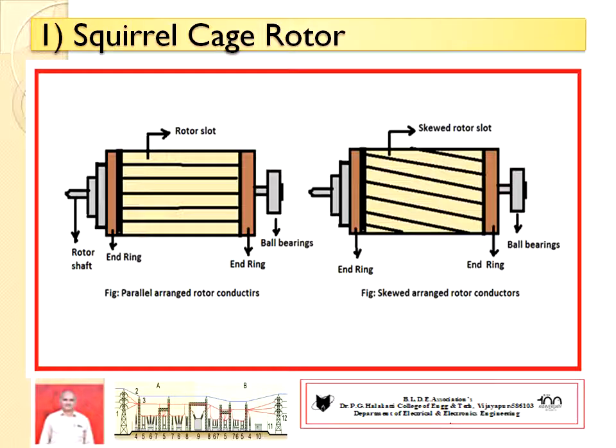This rotor circuit is completed by two short circuit end rings. You observe very clearly the rotor bars both ends have been brazed by end rings which provide a complete rotor circuit. These are also called short circuit rings. These end rings have been made of copper conductor material. You can observe in the figure.